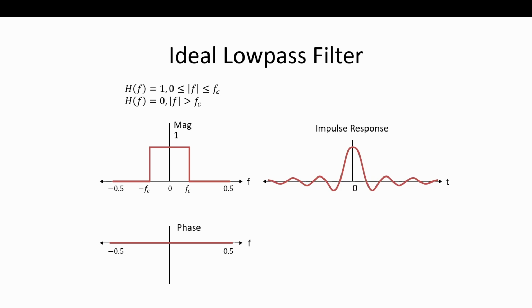It's completely non-causal right now. So we can't realize it in actual implementation, but we can do it in post-processing. We can implement zero-phase filters in post-processing, and we have a result that lines up on both sides, right? That's the benefit of it. But we can't do it in actual implementation because it's completely non-causal.